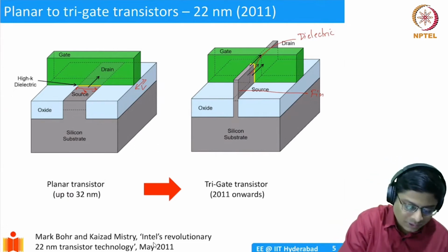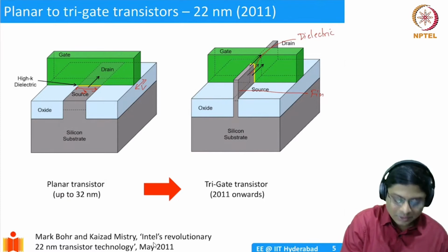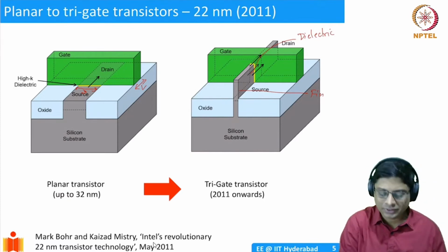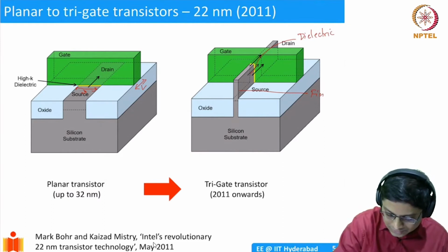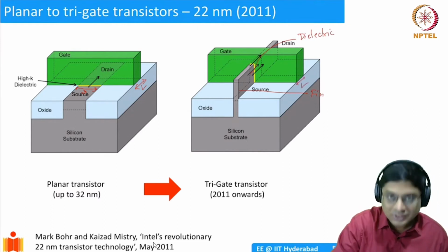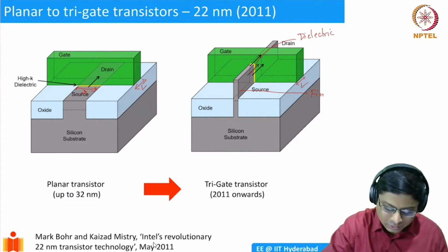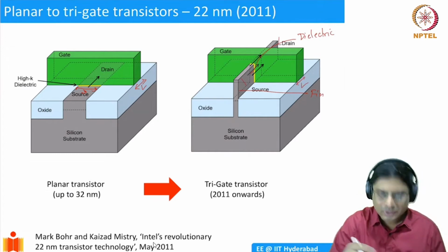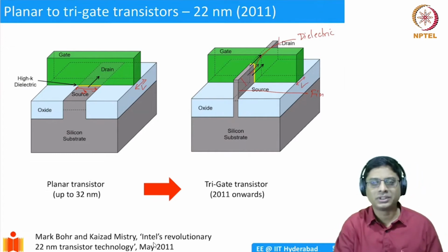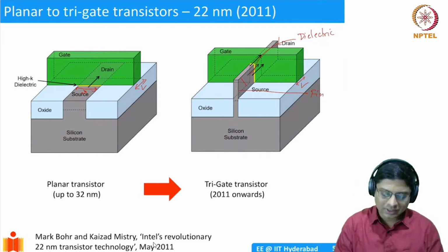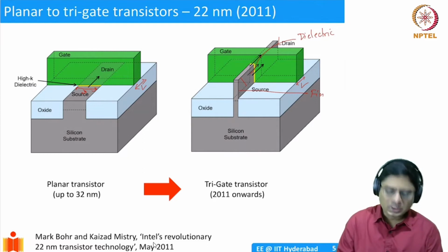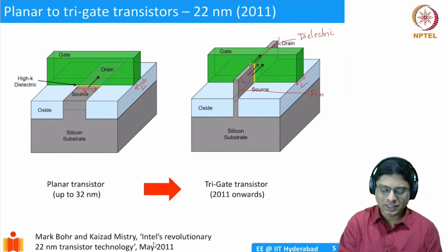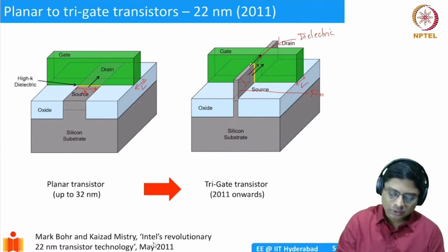So what will be the width of this device? If you relate it to the traditional width of a transistor, what will it be? We can clearly see that this is the length, because it is the distance between the source and the drain. The silicon source is here, the silicon drain is here. Of course, it is doped. And under the channel, there is no doping. So now, it's opposite doping, p-type doping, and then n plus source and drains. So this is the length.